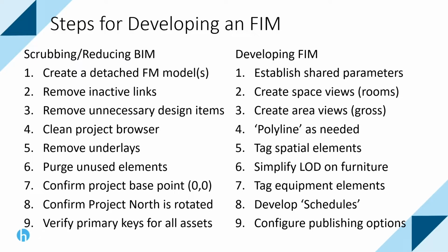I know polylining is not something that you're supposed to have to do with BIM, but the reality is it doesn't necessarily go away. There are still spaces that Revit can't figure out on its own, or you have standards that don't match up with the out-of-the-box Revit functions, and you'll need to actually do some polylining. And there are tools in the BIM models to do that. So there is an element of polylining that you might have to do, depending on your standards.